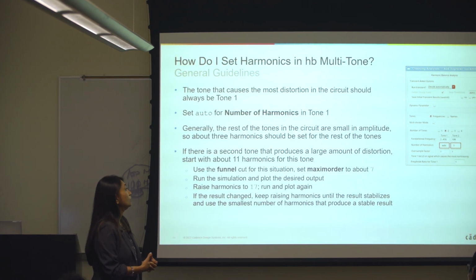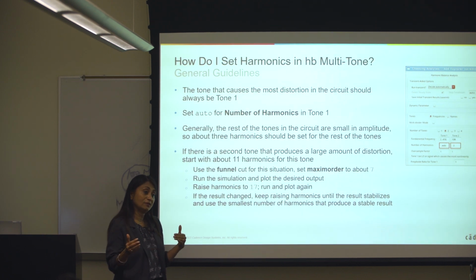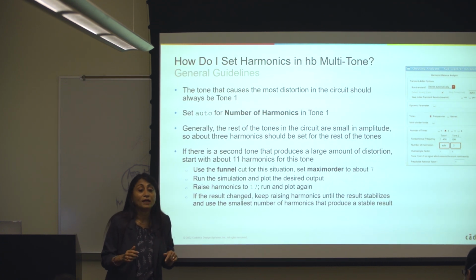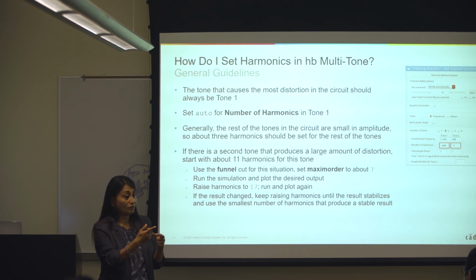And one thing I want to mention, since you brought up mixers: S parameter analysis is great, but it is good only when there is no frequency translation. When your input and output are at the same frequency, SP is great. But why do we have periodic S parameters like PSP? That's because of mixers.